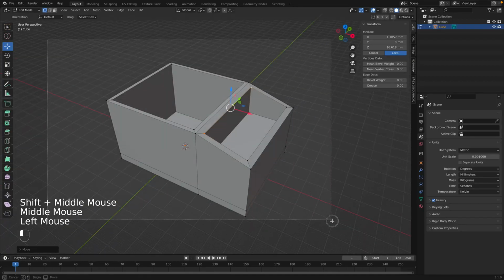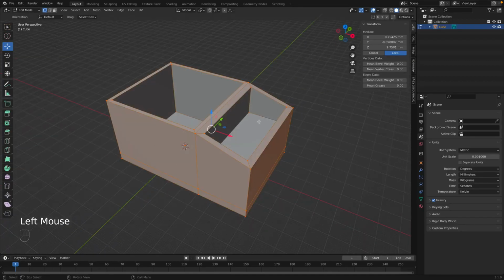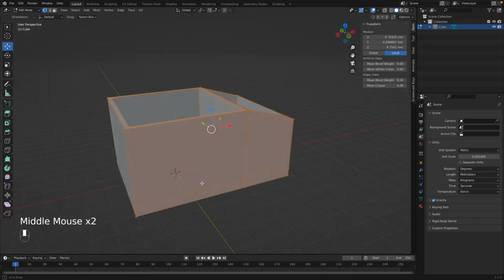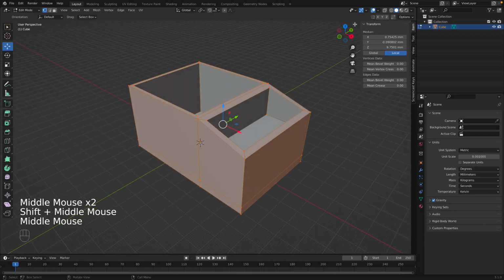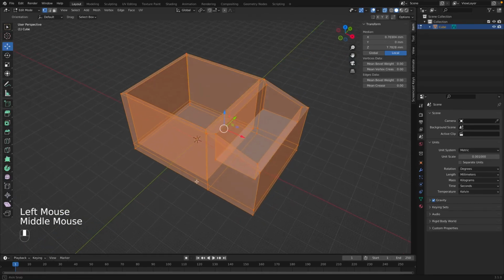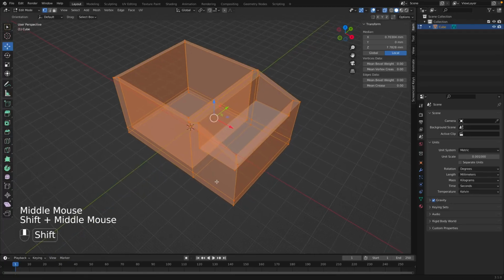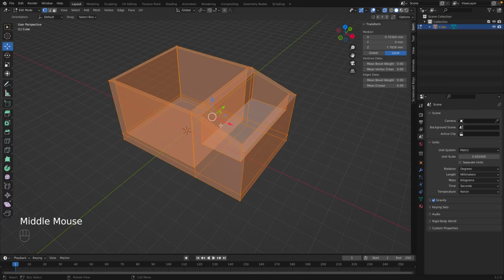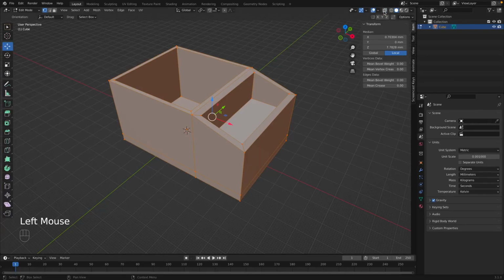And let's say we try to select all of the points. It may look like we have all the points selected, but we actually don't. There's some points in the back or here that aren't selected. So we can see through the object by using what's called the X-ray tool, or the X-ray mode, toggle X-ray. And if we select this button up here on the top right, now we could select through the entire object and select all of the points. So without it, you won't be able to select any points that are hidden in the back. But if you want to be able to see through the object and select all of the points, just toggle the X-ray mode. We don't need that right now.